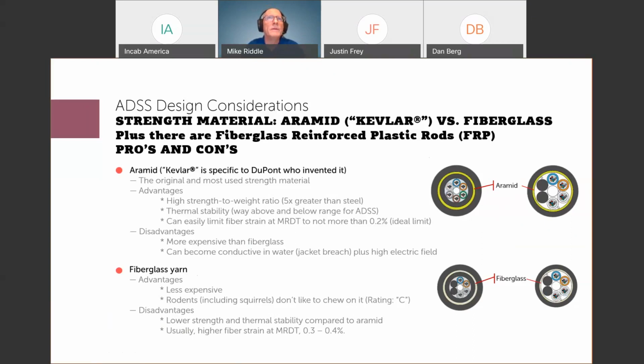And that gave you a low, but not a zero, probability of a fiber failure, expressed as number of fiber breaks per fiber kilometer per year. That number ended up being really low. And so this is still a benchmark used by cable manufacturers around the world.